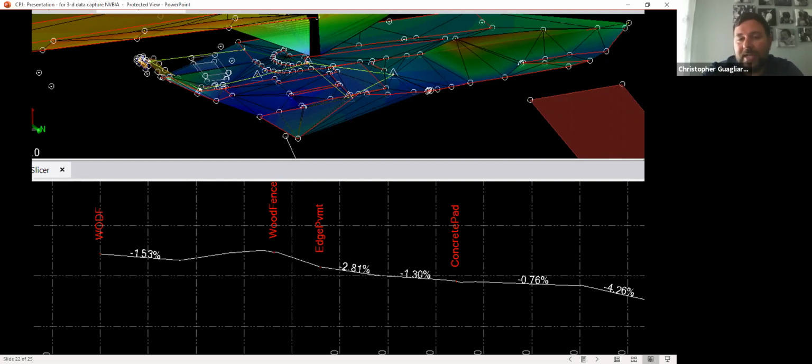So now you know if you're ADA compliant and what's going on. If you're as-built, you have a really quick slope profile, real quick. And if you're just doing an overall look from just seeing what you got, that's how quick you got it. It literally does not take any time to get those profiles out because of the scan. So you don't have to worry about having your surveyor go out there and grab the right points. You have all the points already there.